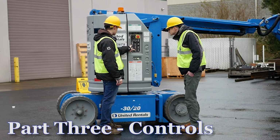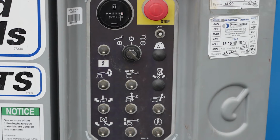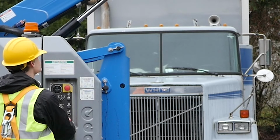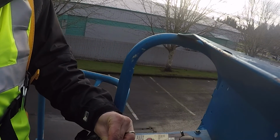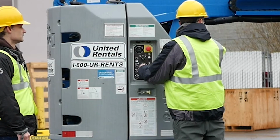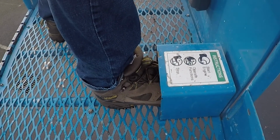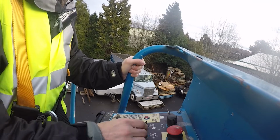The controls on an aerial device will vary from vehicle to vehicle, but there are some common principles. Each aerial lift will have ground controls, and many have platform controls. Aerial lifts require two distinct, and separate, actions to operate the vehicle. This is to prevent accidental motion. The ground controls require a function switch to be held to one side, while the other controls are activated. The platform controls usually have a foot pedal, which must be pressed while operating the controls. If the function switch, or the foot pedal, is released, the vehicle will stop.